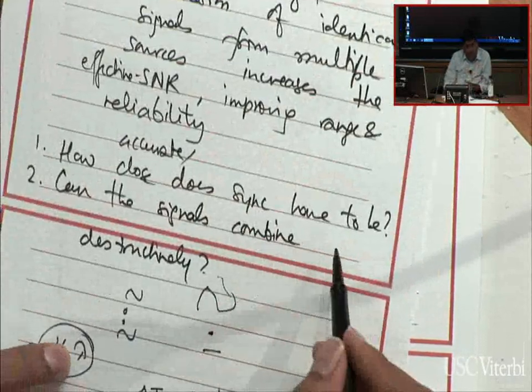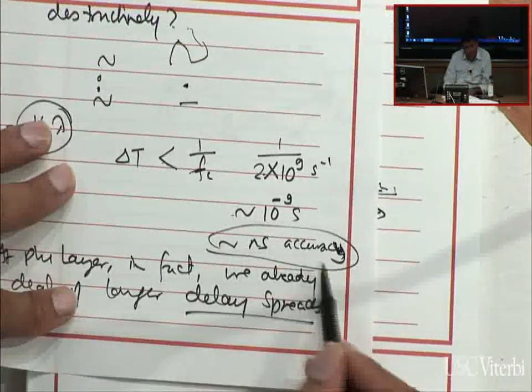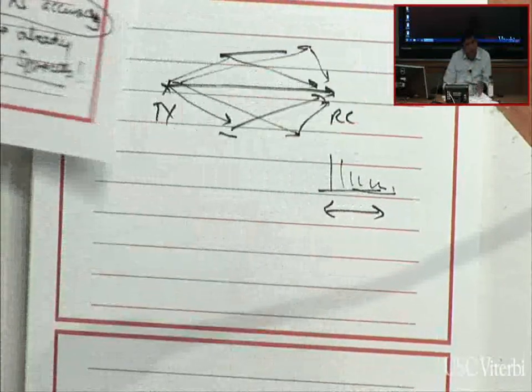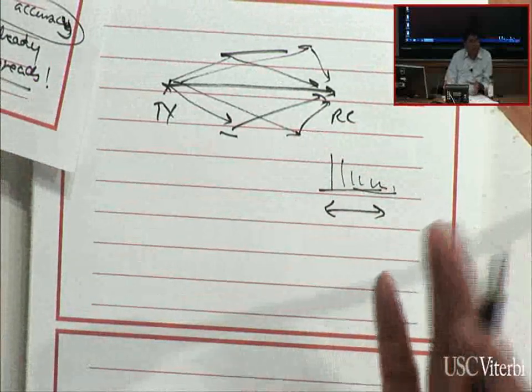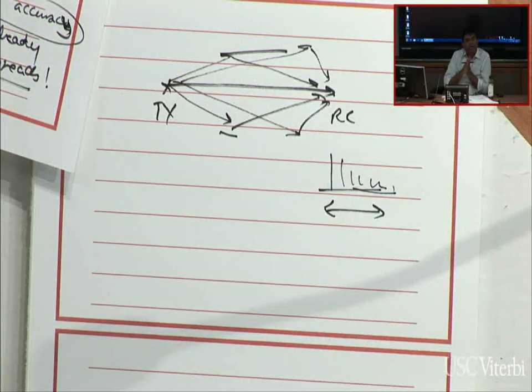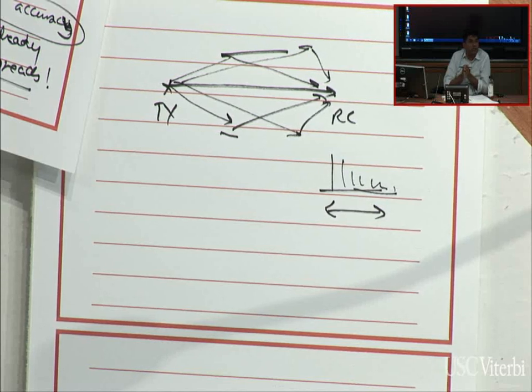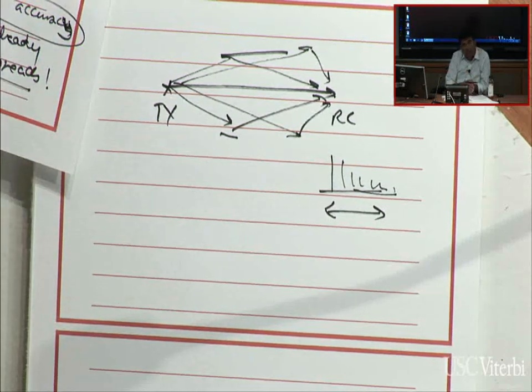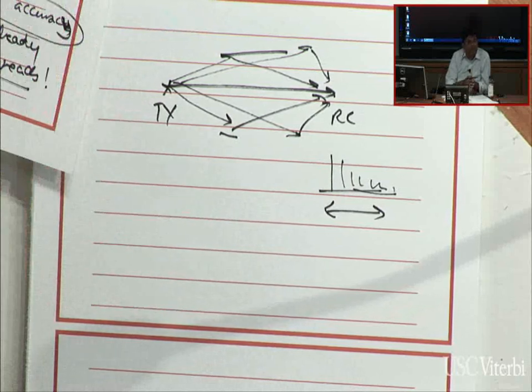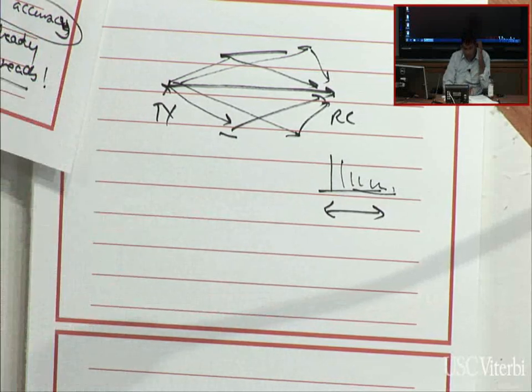And so even in this environment, even if they're not, in fact, nanosecond level synchronized, there are physical layer mechanisms which can mitigate a lot of that delay spread that's going to end up happening. So you can think of the slight asynchrony as being equivalent to delay spread. And so techniques that are deployed in wireless systems to deal with delay spread, and the equivalent of that in the frequency domain, called frequency selective fading, can also be applied to receivers for cooperative systems.